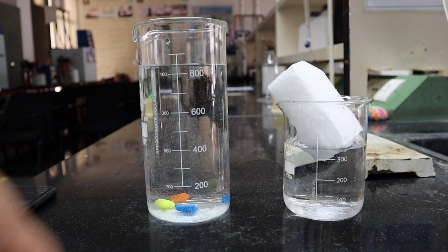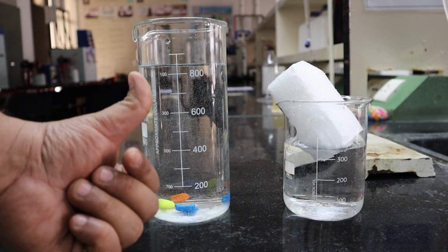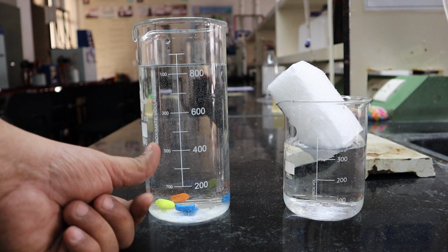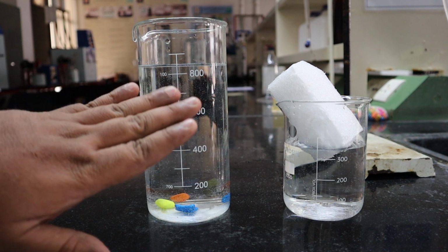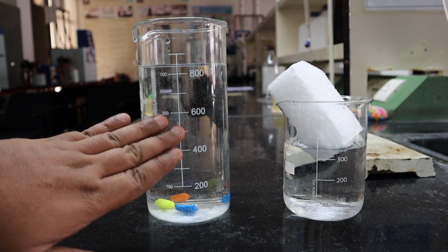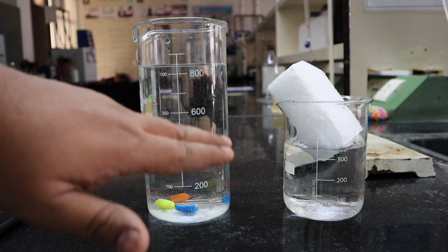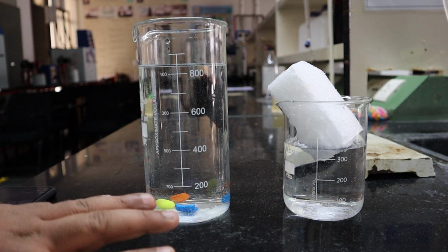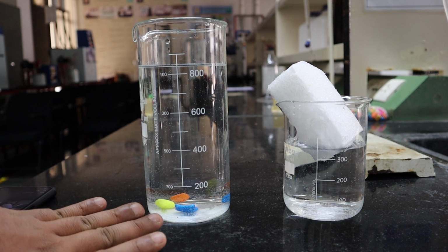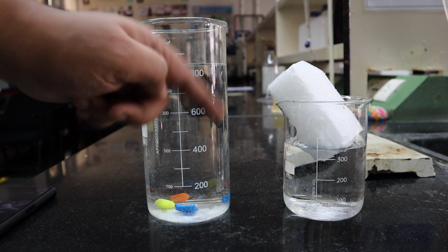I told you there are three forces. One is the gravity force, and the two forces that act opposite to gravity are buoyancy as well as drag. The drag in still conditions is very low, because if the water is moving in the upward direction while the pebble is moving downward, in such a condition the drag will be very high. At this point the drag is very low, and the gravity force is m into g, which you can calculate.